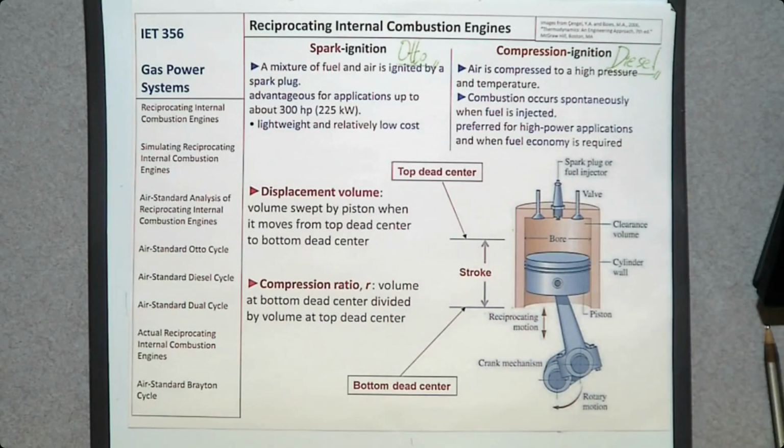Then, is that the only difference? So it sounds like, except the low cost, everything is good about the diesel engine. Is that right? There is another thing that we need to consider. If you only talk about the energy conversion point of view, the diesel engine might be more beneficial because it has a higher efficiency. You pay less fuel, and then you produce more power. But there's also a downside.